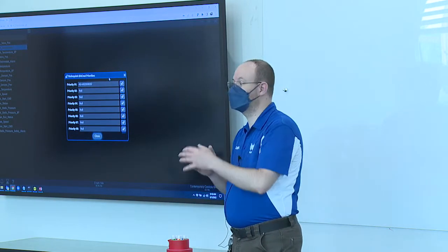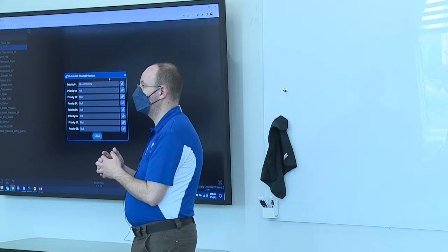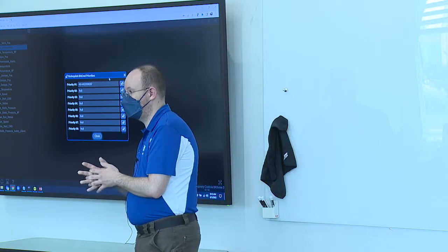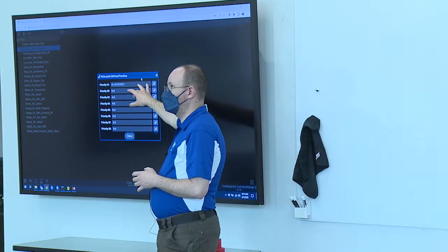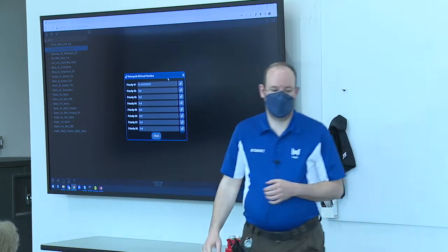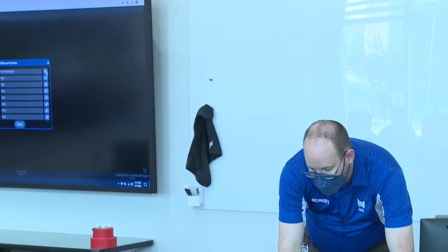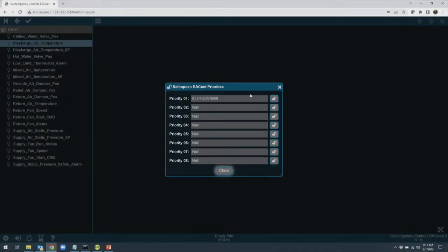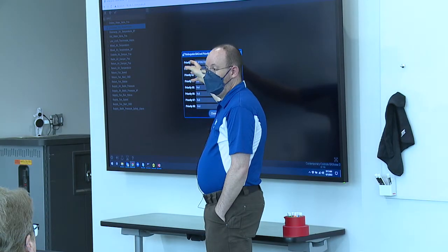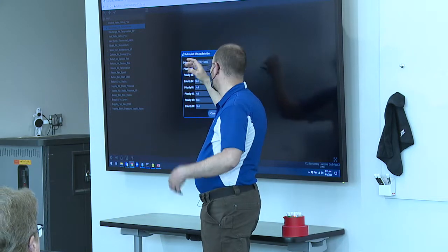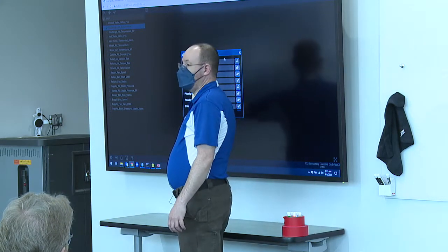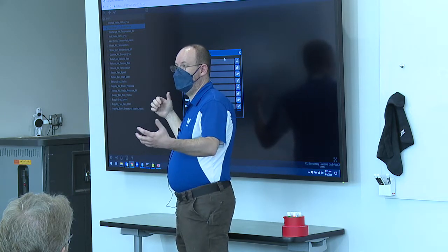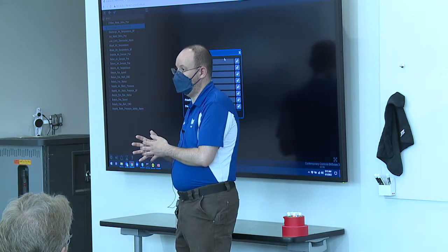So we cannot change the priority here. It's just the priorities of the controller. Correct. We can lock it. I don't know what that button does. Hang on. Your administrators can go in and do it. As soon as you hit that lock button, it will wipe out whatever value is there and replace it with null. But if, on the controller side, something rewrites that value after you've set it to null, it's going to go back to whatever the controller wrote it as.